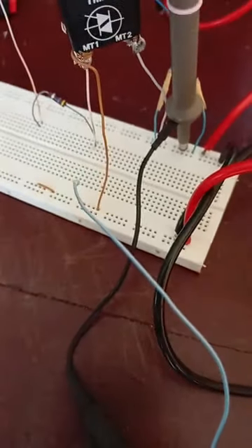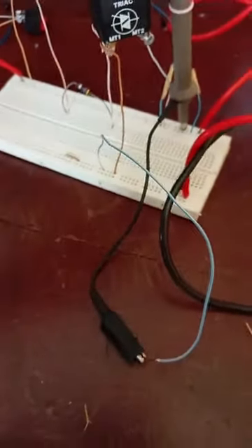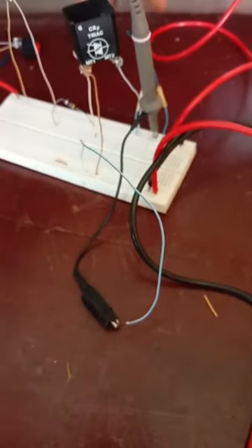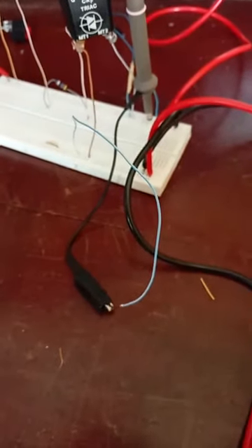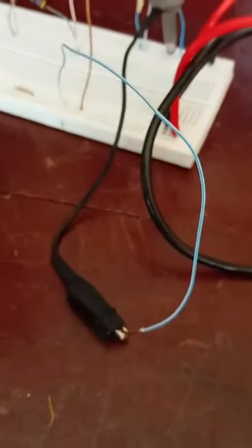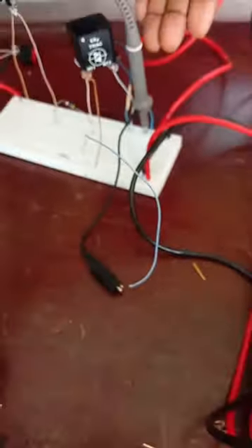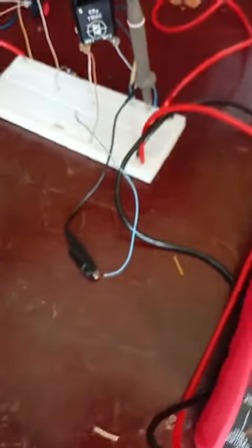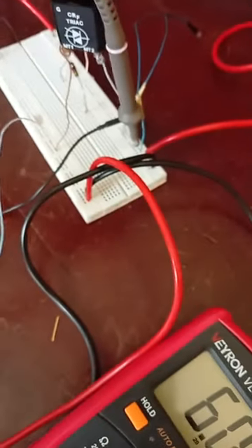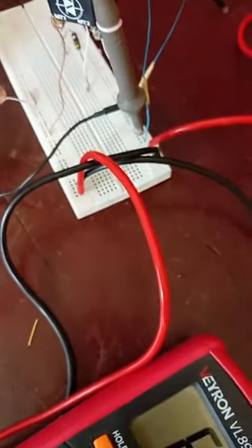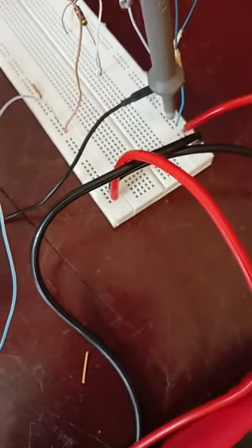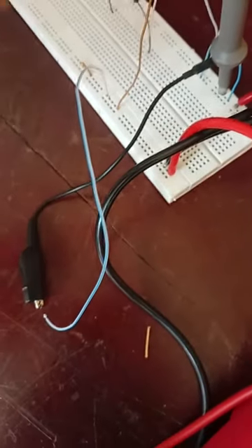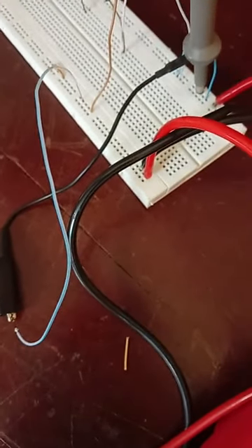Now what I want to do is, this is our miniature lamp. They say we should put the oscilloscope to it. You can see that MT2 is the output. We put our oscilloscope positive, and the negative to the ground. So we will bring out the ground from the negative of the oscilloscope, and the positive of the oscilloscope from one terminal of our lamp.